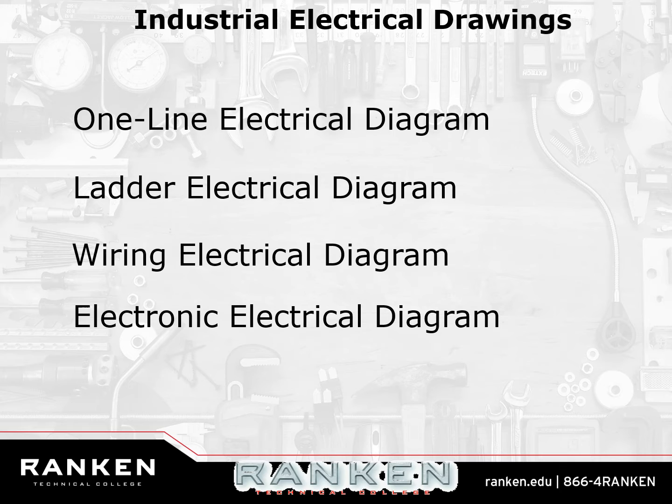Okay. Wiring diagrams are used to actually wire the thing up. How do I wire this up? You go from terminal 13 on the relay on wire number 7. It starts out as wire number 7, goes to terminal 13. It comes out of terminal 14 and becomes wire number 8. Wire number 8 goes to terminal A1 on another relay, right?